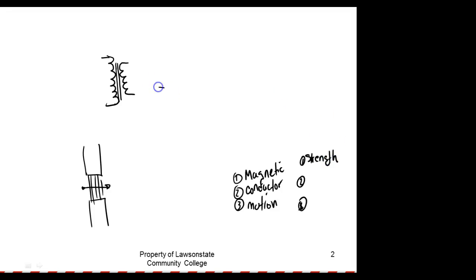If we think about it, when I move a certain direction, each one of these windings is basically acting like one of those. It's just that we're constantly turning. So if I wind these things up in the same direction, we end up with that right there. Every one of those little windings would produce a little tiny EMF, but if we wind them in the same direction, those little EMFs are in series. Series DC sources add together. So we just put a bunch of loops.